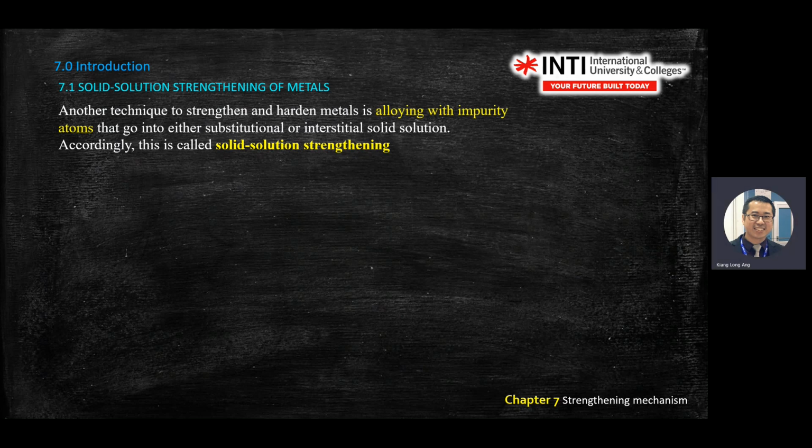Previously, you learned about defects, right? Defects, you have a hole and also an extra space there. So substitutional means you replace the atom, and interstitial means you find the gap between the atoms or molecules, and then you fit inside there. Previously, there was an example to calculate the space for the atoms that you fit inside the crystal structure.